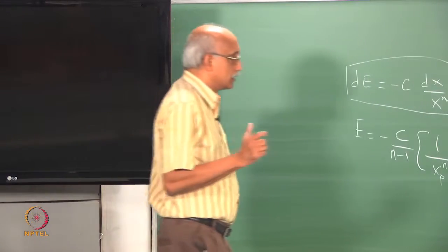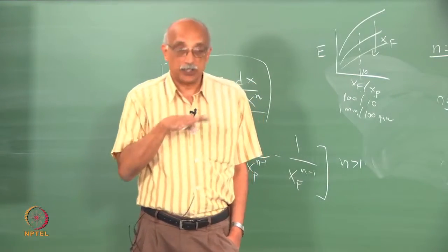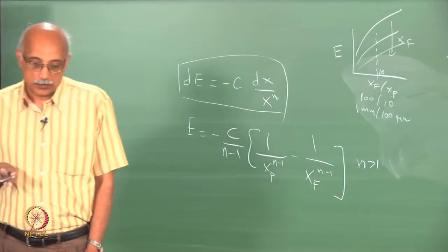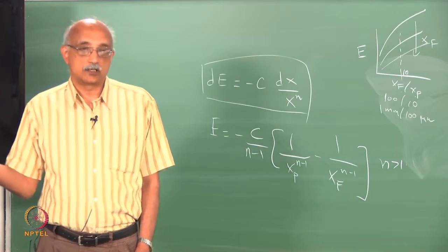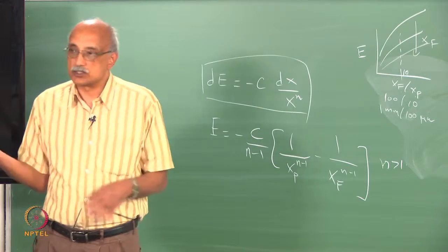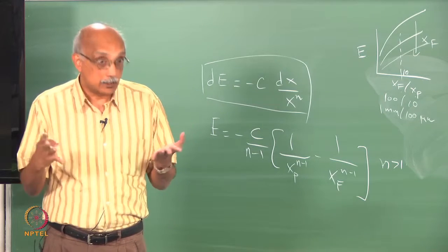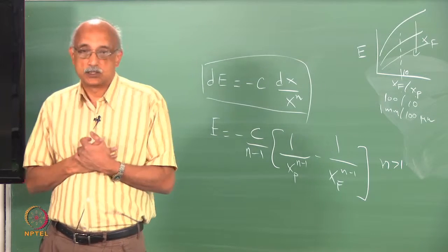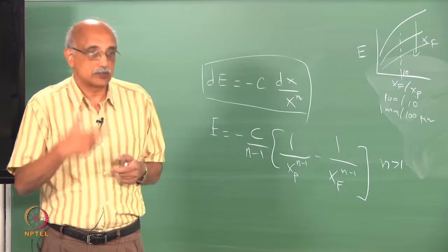So, you have to be careful with your understanding and application of these laws, in the sense that the energy required to create new surface keeps increasing as the particle size becomes smaller and smaller. That is a key thing that you have to realize in size reduction by mechanical means. It takes a lot more work to break down particles to finer sizes as you keep proceeding with your size reduction.